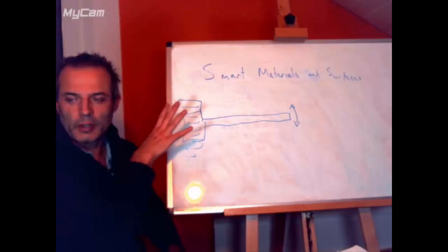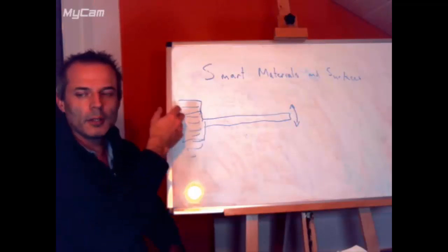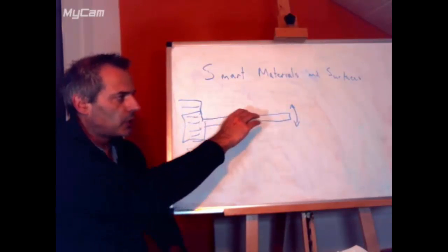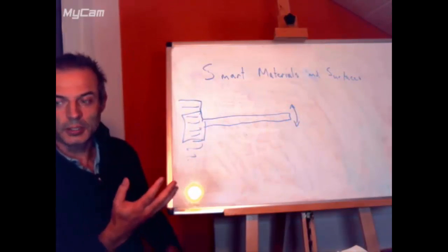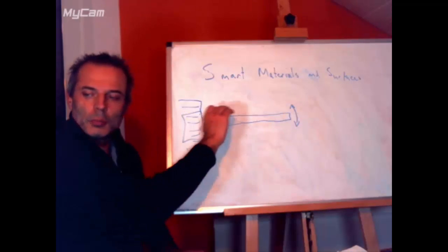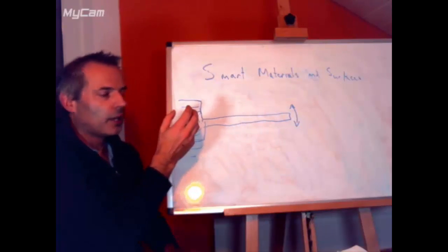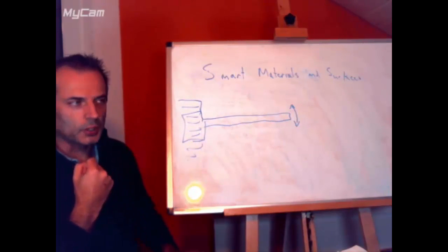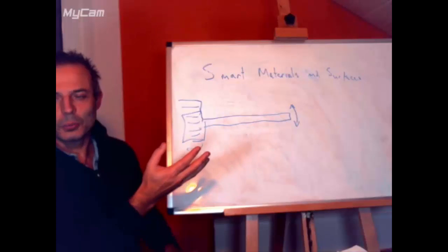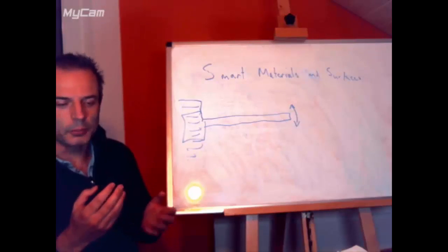We have to hold it by a very massive or very stiff clamp here on the end, or however we're going to hold it. Usually they're micro machined out of a single piece of silicon so that they can then oscillate. We also have to be able to excite it some way, which isn't so easy. Some of the ways would be having two different materials on here and then heating and cooling it, or applying a voltage or something, and then we need to be able to read what frequency it's oscillating at. So the advantage in understanding goes away a little bit in the complexity of how it works and how we're going to measure from it.